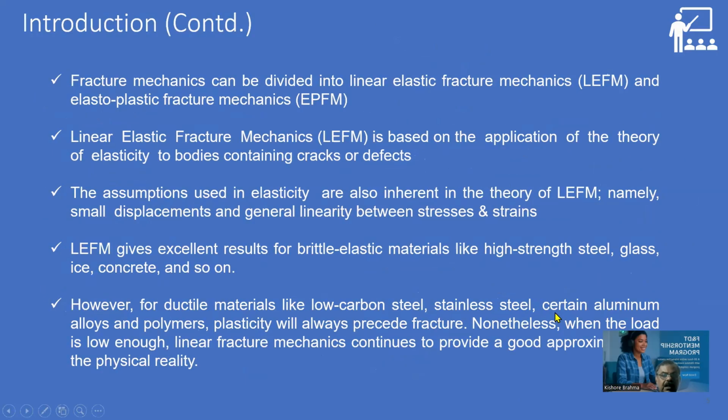So, fracture mechanics can be divided into linear elastic fracture mechanics and elastoplastic fracture mechanics. Linear elastic fracture mechanics is based on the application of the theory of elasticity to bodies containing cracks or defects. The assumptions used in elasticity are also inherent in the theory of linear elastic fracture mechanics, namely small displacement and general linearity between stresses and strains.